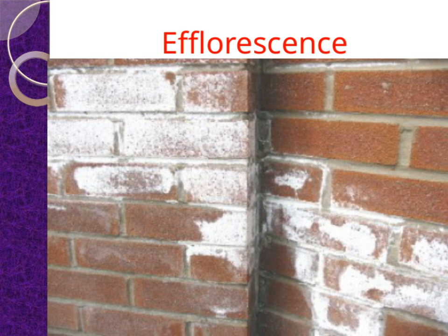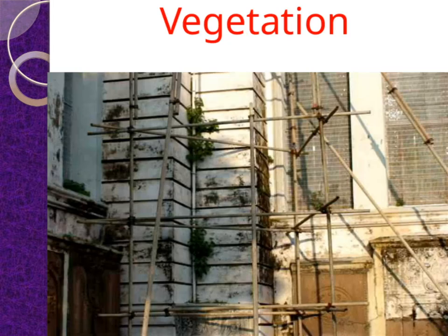In the context of building maintenance and preservation, understanding efflorescence helps us assess the health of a structure and plan appropriate interventions. While it can often be cleaned off, preventing its return is key, which means managing water infiltration and improving drainage are vital steps. Overall, recognizing and addressing efflorescence fits into our broader goal of maintaining durable, stable, and aesthetically pleasing structures. Let's take a closer look at vegetation.